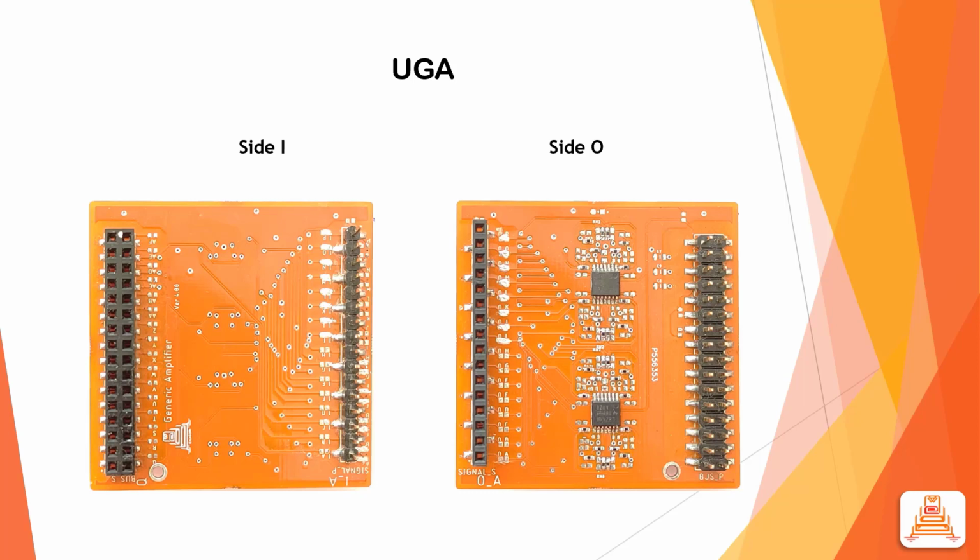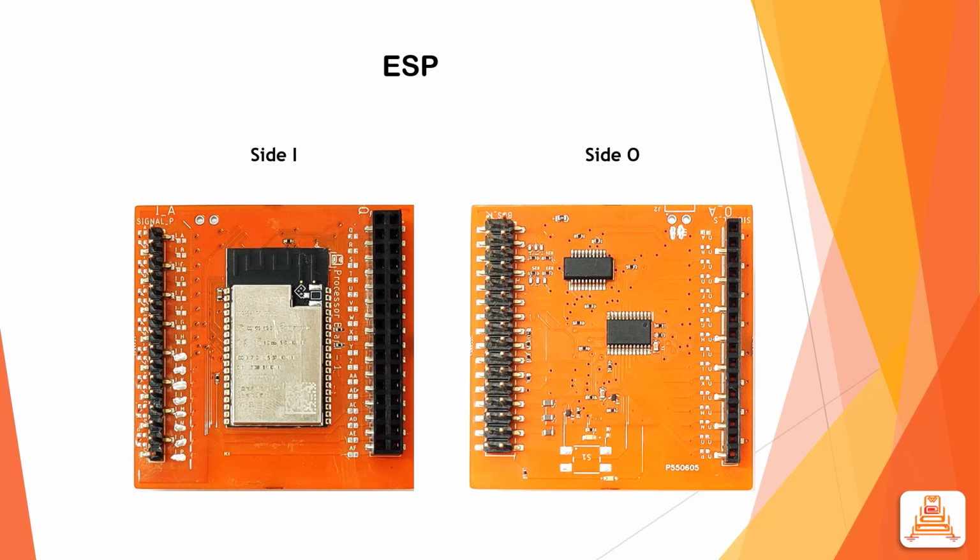Finally, all the outputs will be available in O1 through O8 of the unity gain board. These are taken into the ESP32 processor board by shorting the jumpers I1 through I8. The microprocessor will sample this through the mux.